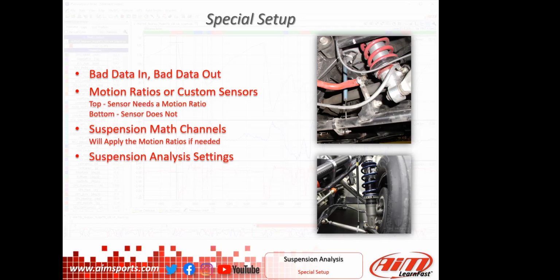If we don't do that, all of these adjustments you're going to make, at the other end of this hose right here, there's a canister that has the adjustments for the rebound and compression damping. If I am making adjustments on this inch of travel here when we're actually moving a little over 3 inches over here, we're going to make some false choices.